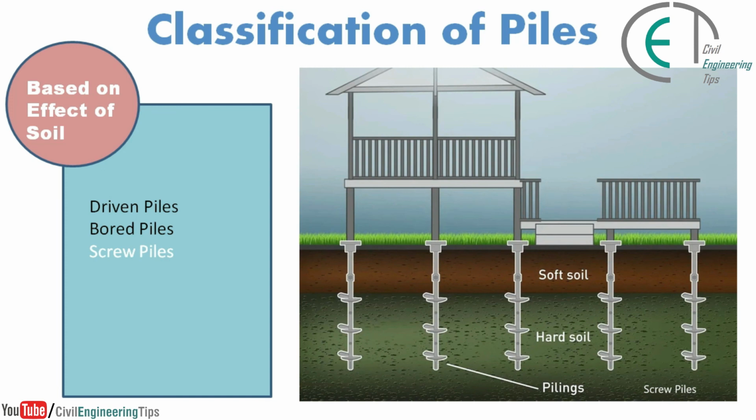Screw piles. Screw piles are a type of deep foundation that can be installed quickly with minimal noise and vibration. Screw piles are wound into the ground much like a screw is wound into wood. It is an efficient means of installation, and coupled with their mechanism of dispersing load, provides effective in-ground performance in a range of soils, including earthquake zones with liquefaction potential.